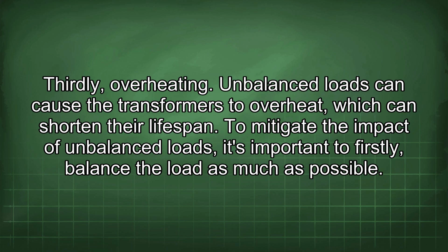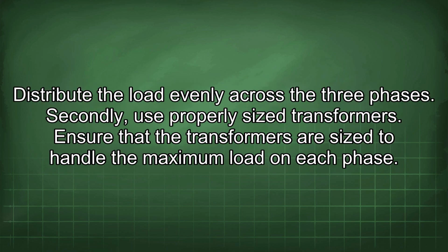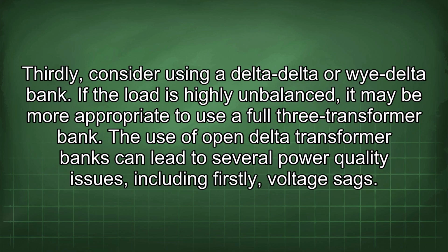To mitigate the impact of unbalanced loads, it's important to, firstly, balance the load as much as possible. Distribute the load evenly across the three phases. Secondly, use properly sized transformers. Ensure that the transformers are sized to handle the maximum load on each phase. Thirdly, consider using a delta-delta or wye-delta bank. If the load is highly unbalanced, it may be more appropriate to use a full 3-transformer bank.